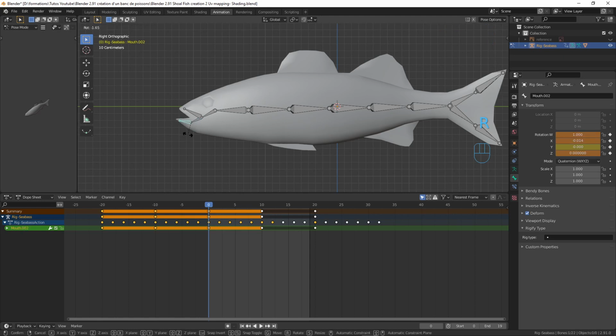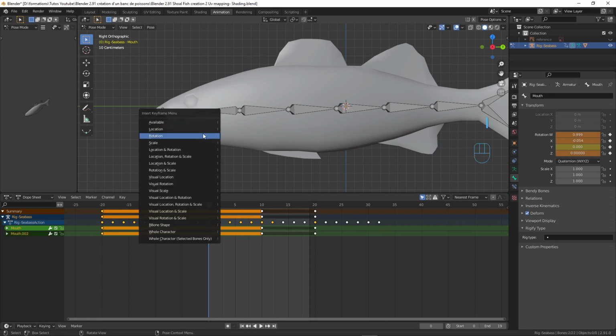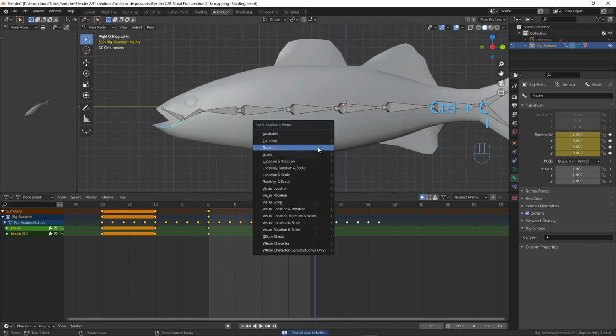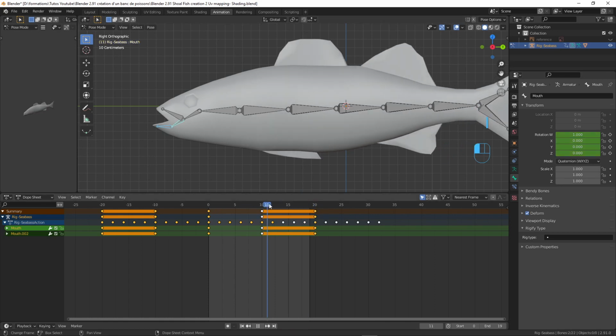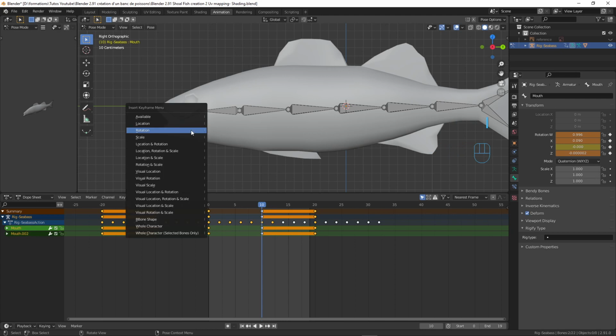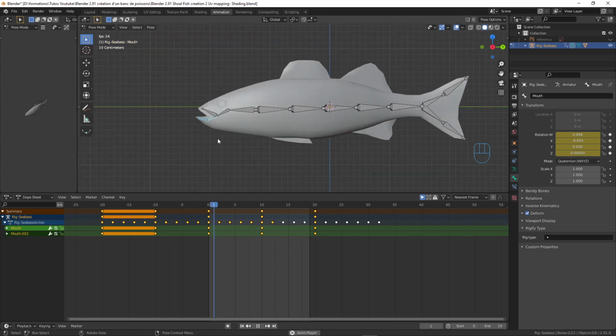And there's two bones that we will manage. The one on top doesn't move usually. So, okay, there's two here. I insert a key of rotation. This one will be the same because it's the same as we did already on the 0 and the 20. So I make Control C, I go into the 20, I insert a key of rotation. And now I come back into the frame 10, and to make it open this time, I open it just like so. Okay, and I insert a key again of rotation. So now I have a movement of opening at least.